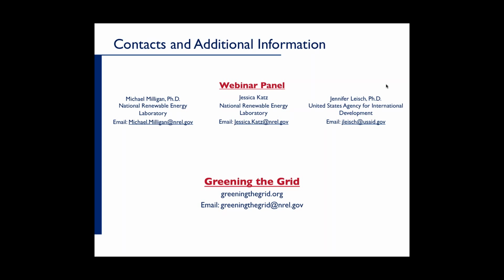And I think the other interesting source of flexibility is coming out of two different sources. Aeroderivative turbines, which are basically jet engines which are turned into generators. They can ramp very quickly, they can start very quickly, they have minimal heat rate degradation at startup and over the ramping cycle. They're pretty efficient. And so that's one source of flexibility.